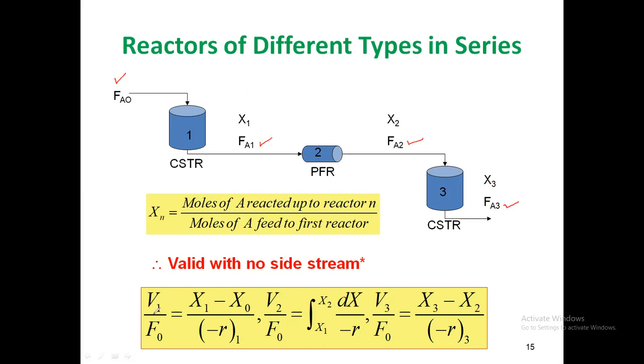So originally, if you're going to write it for the first tank, your CSTR, that would be V sub 1 divided by v. So I'd like to write the volumetric flow rate here. It would be the same for all. The same volumetric flow rate equal to CAO minus CA1, and you will have here rate 1. Okay, so that's for your first reactor.